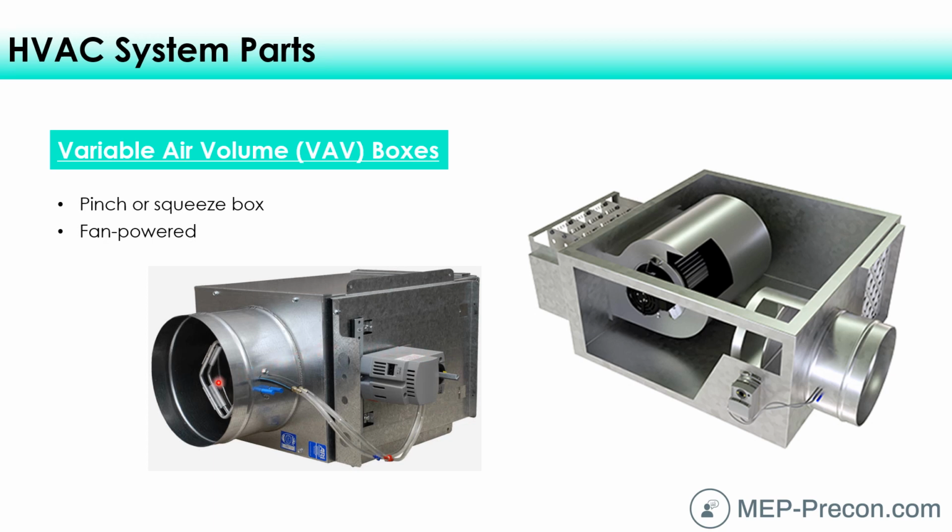It doesn't close completely. It just closes to some point because we still want a little bit of fresh air to come through the system just to keep it from getting stuffy and to prevent carbon dioxide buildup, what we breathe out, because within a space, as you exhale, if you get a lot of carbon dioxide buildup, you get kind of tired within that space. And so we need to have a little bit of fresh air in there. Code usually requires a little bit of fresh air within the space anyway.